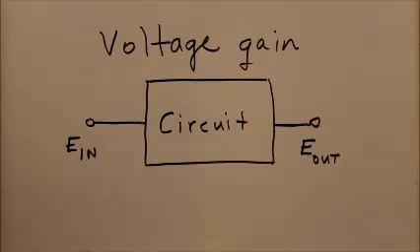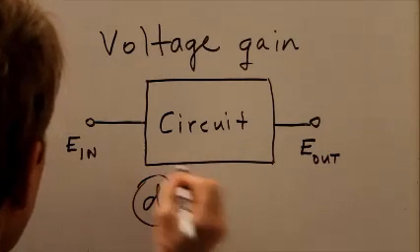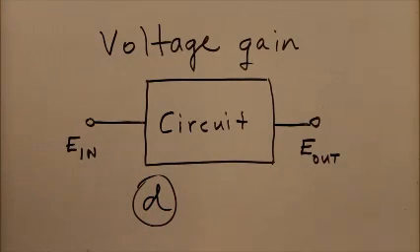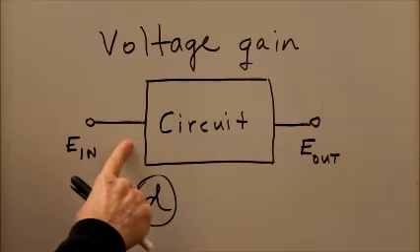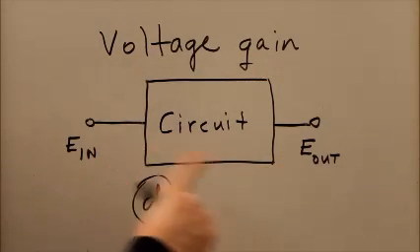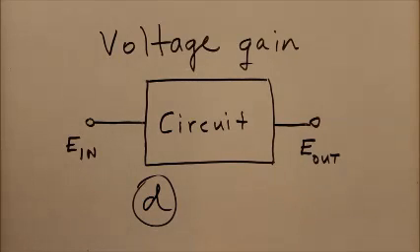Well, the short answer to this question is D, more than one of the above characteristics. So it's got to be one, or it's got to be two or three of the A, B, C above. Well, as things turn out, it's A and B. We must be sure that there is no reactance in the input or output impedance. That is to say, they have to be both pure resistances. And in addition to that, they have to be the same resistance.